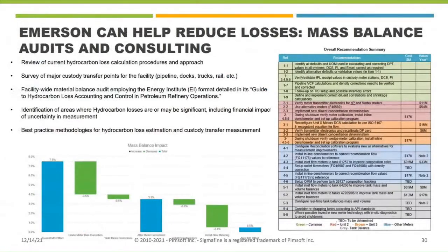In this specific case, the baseline was very poor, showing an initial imbalance of 7.5%. Measurements compensation greatly improved the balance, and so led to a 4% reduction. And an additional 3% reduction was achieved by installing new meters. So finally, the resulting imbalance was in the range of 0.5%.